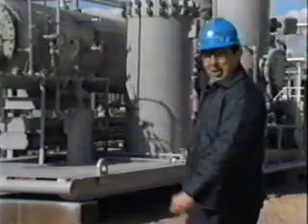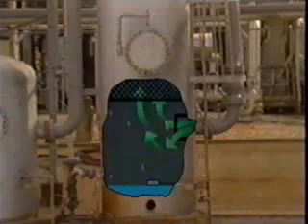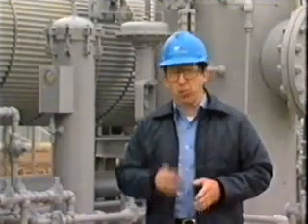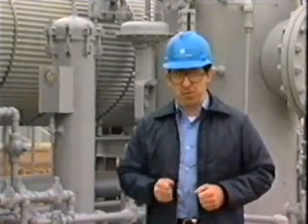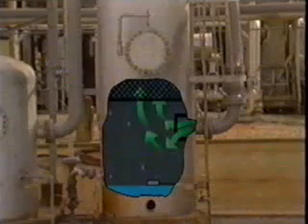The upper system regulates the flow of liquid hydrocarbons discharged from the vessel. The lower system regulates the flow of glycol from the vessel. Filters are installed in the glycol stream to remove solids and other contaminants which may cause plugging and foaming. There are two types of filters commonly used in gas dehydration systems. One type is used for solids removal, and the other for dissolved contaminants removal.